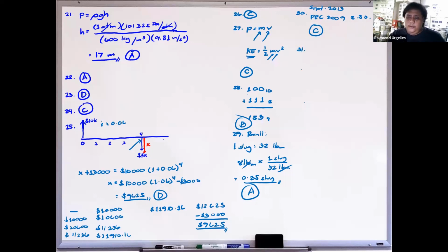If you go beyond 25 ohms, that is already considered high impedance. So you need to bring it down by connecting the electrodes in parallel. Okay? So next, number 31.